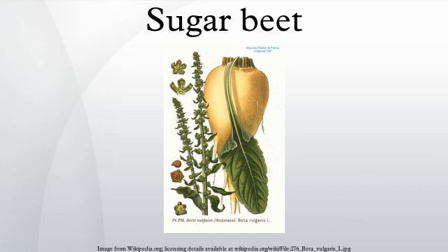The beet is moved from the heaps into a central channel or gully, where it is washed towards the processing plant. Diffusion. After reception at the processing plant, the beet roots are washed, mechanically sliced into thin strips called cossettes, and passed to a machine called a diffuser to extract the sugar content into a water solution.